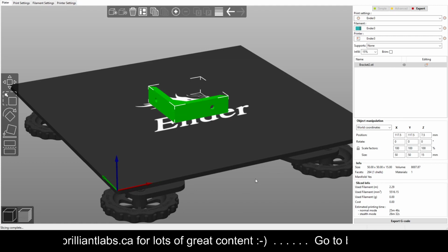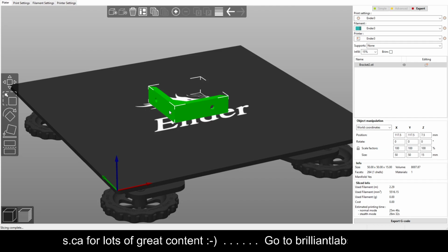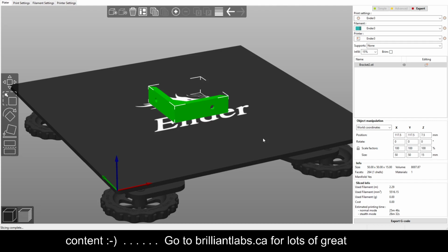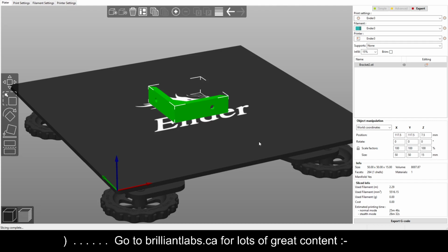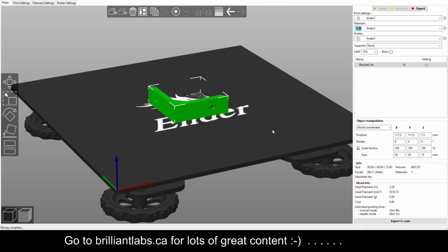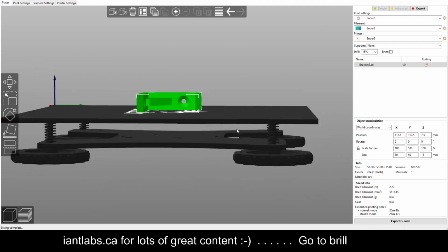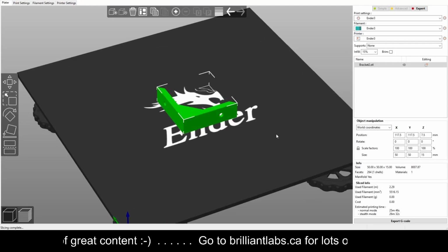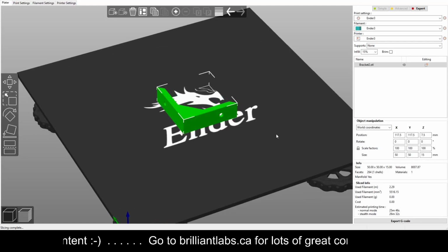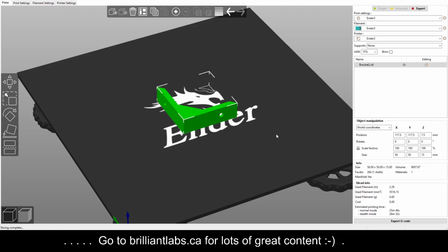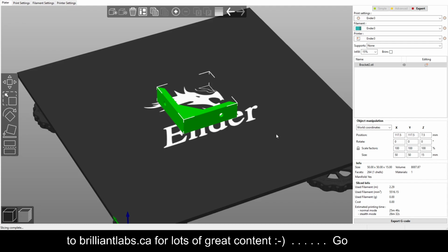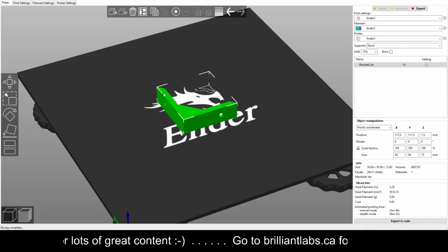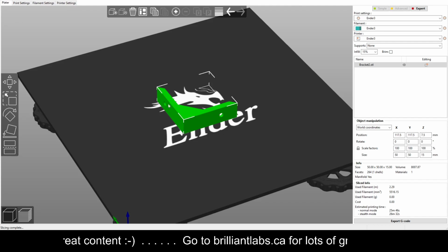The neat thing about most slicers is that if you decided you need this in a little bit of a bigger format, you could scale it right in here. You could flip it over and so on. I want to talk a little bit about how we're going to print this one. The weakest part of a 3D print are the spaces, or how layers are attached to each other. So this is the best orientation to print this in, so that the printer will have continuous lines all the way around the corner.